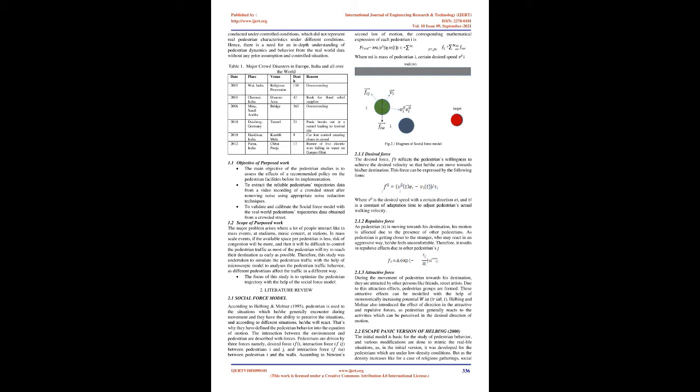It becomes a big problem at bigger densities, particularly in a nation like India, if the pedestrians do not act consistently and orderly. In addition, collective dynamics will be created from individual human nonlinear interactions in pedestrian dynamics. For instance, a crowd in ordinary circumstances forms self-organized patterns such as lane formation, oscillatory flows at bottlenecks, and stripe formation in intersection flows. Under extreme circumstances, however, coordination will fail, leading to new phenomena such as freezing by heating, faster is slower, and crowd turbulence.